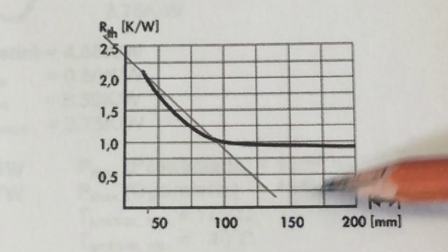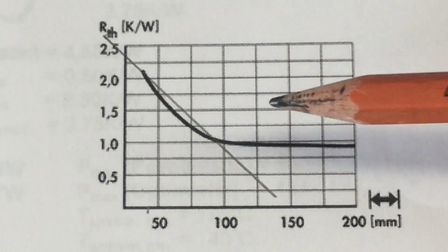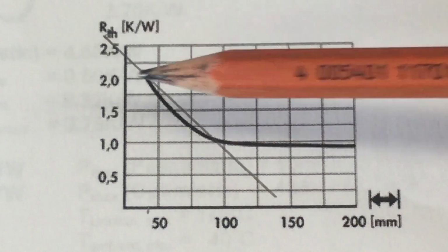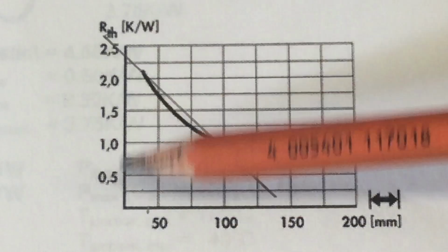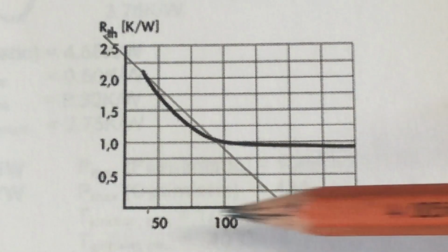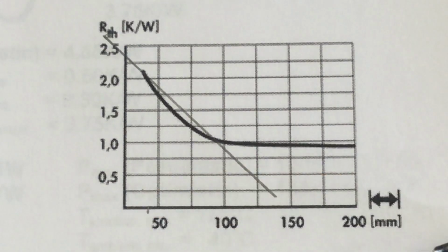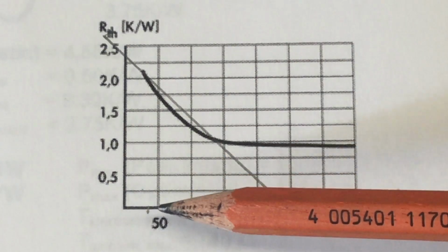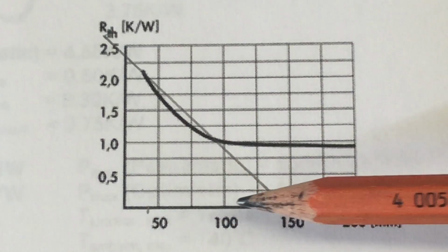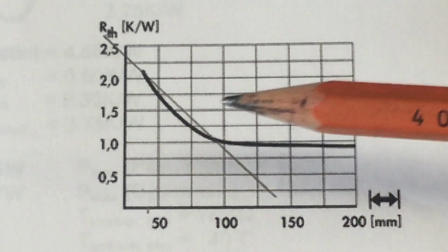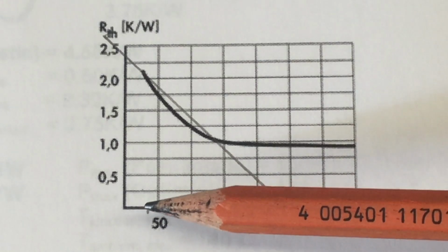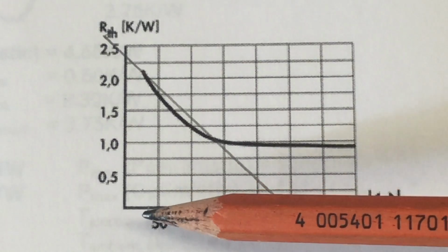First, I could have had a look into the data sheet of the heatsink, because the manufacturer included there a curve where you have the thermal resistance in relation to the depth of the heatsink profile, because they sell it not only in 50 millimeters, which I bought, but also in 75, 100, 150 and 200. And I cut down from 50 millimeters to, what was it, 36.